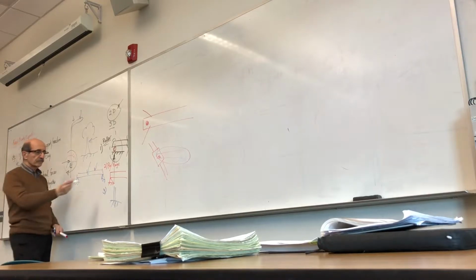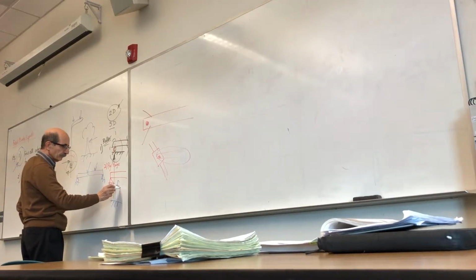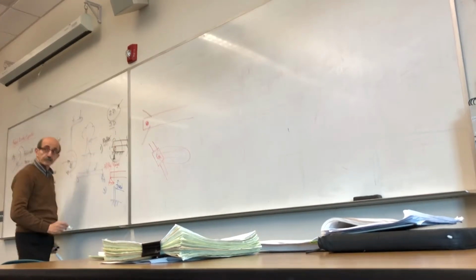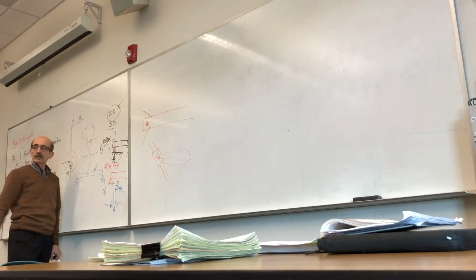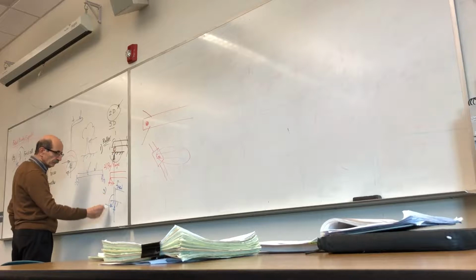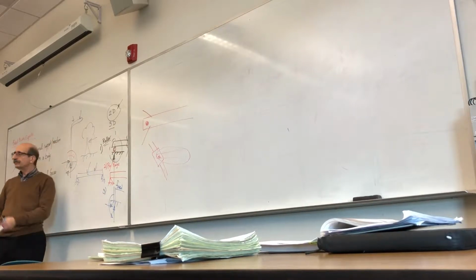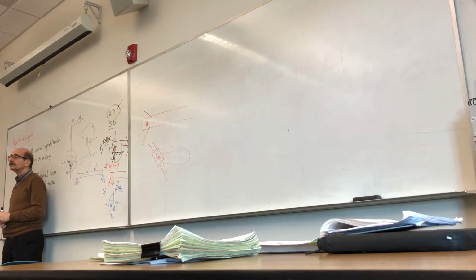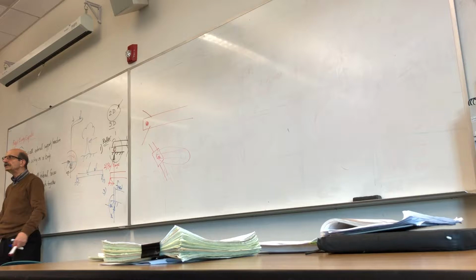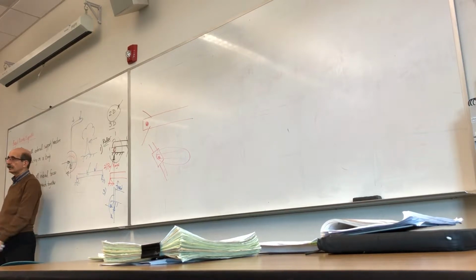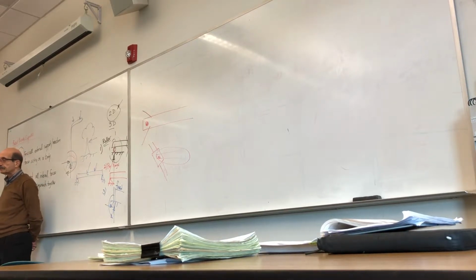So we call this a fixed end support, which means there are three unknown forces and moment that are resisting the motion, rotational and translational motion in all directions. So in 2D, we have no more than these three types of connections.